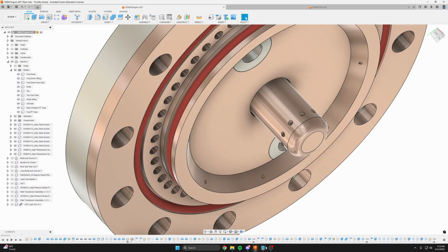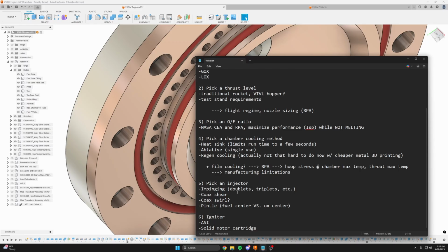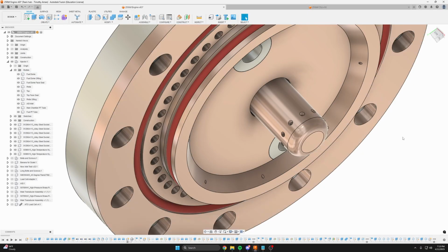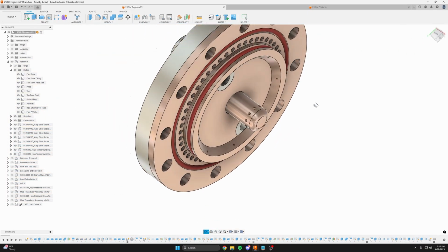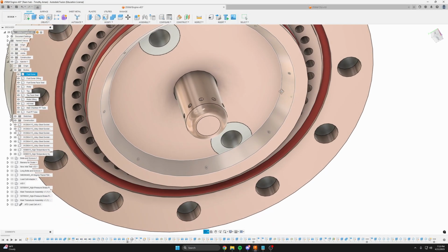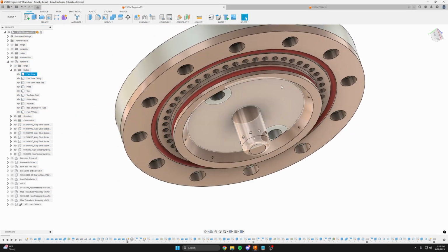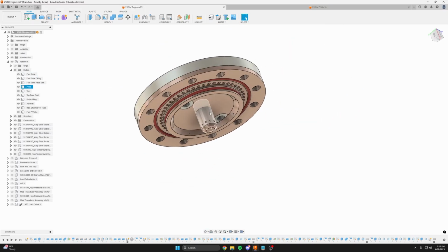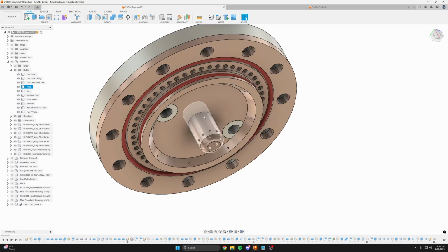Those are also fairly easy to machine and design, and if the inner holes are too small to machine, you can buy little needles or something, and then sort of bond them somehow to the injector face and inside of the annulus. And if you have multiple elements, it helps spread out the propellants throughout the combustion chamber, whereas with a Pintle you just have one singular Pintle element.